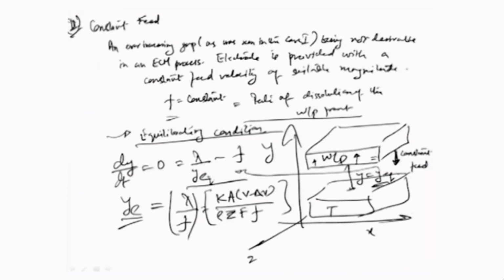Now let us slightly change the paradigm. Because ECM as a process is eventually to be applied to microsystems, the whole kinematics or dynamics of the process should be made at least scale independent. For that, we need to non-dimensionalize the equation so that, irrespective of the scale, known by its length scale, time scale or velocity scale, everything is ratiometric in comparison to these scales.